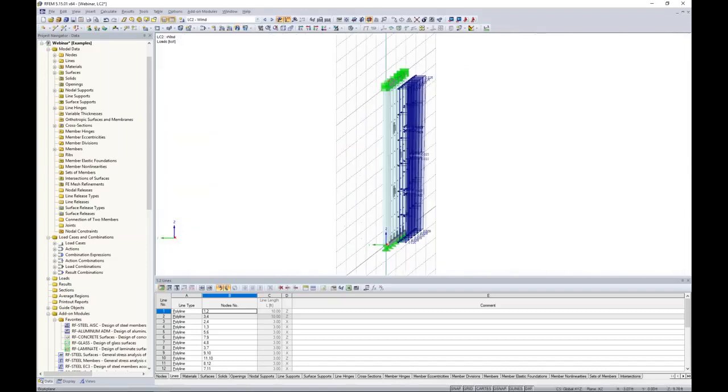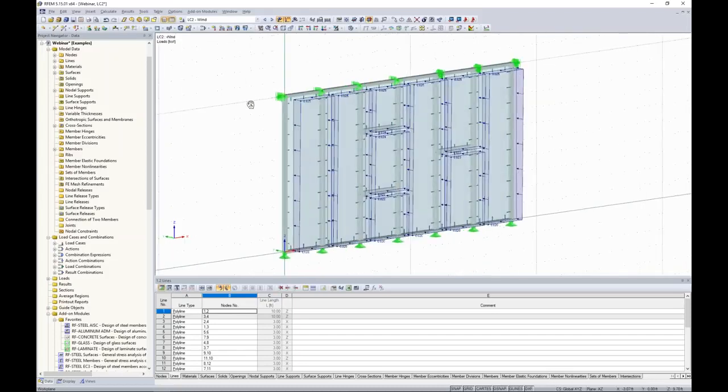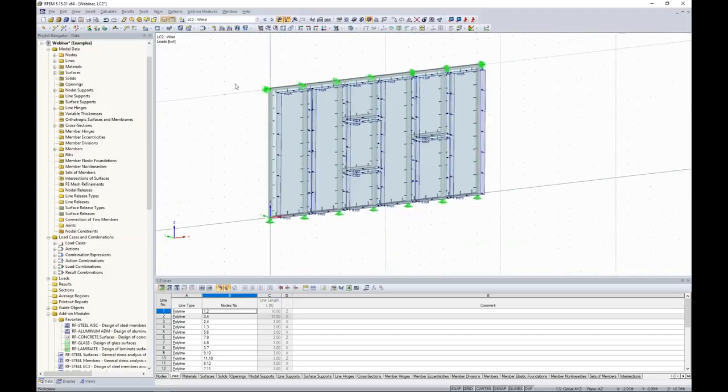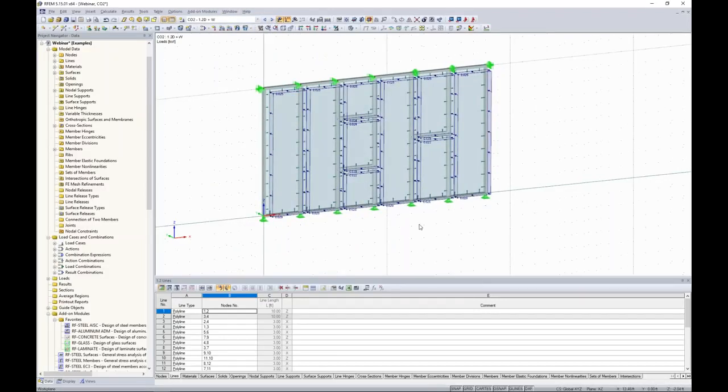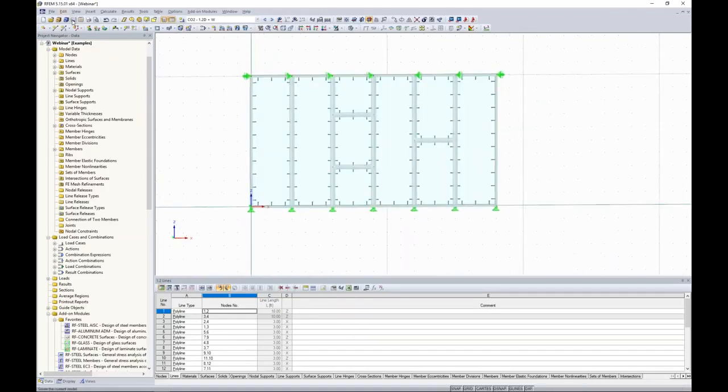And just like that, we have our wind load applied to the surface here, which is varying in the Z direction. So pretty simple for our loads being applied today. We can see the load combinations here with the load factors applied for dead load and wind load and so on.